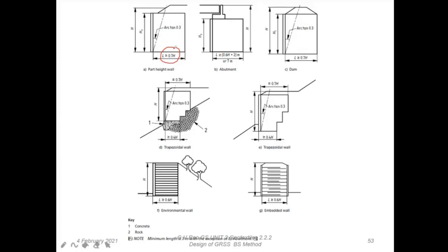So what we are trying to look at is, in this mass, what do we know? As of now, we didn't place a reinforcement, but reinforcement is going to be light only. It will be definitely lighter than the soil itself, the fill material. But then we would have a selected soil in this case. To begin with, let us say we are going to pick up sand, coarse sand. Just assume that now. For coarse sand, conduct a compaction test now and find out the so-called OMC and MDD. And so we are going to use the MDD value of that now. And if we know that the height is h now, we can find out the total weight of this mass now. Okay, we know the shape now, so we can find out the total mass of this entire thing.